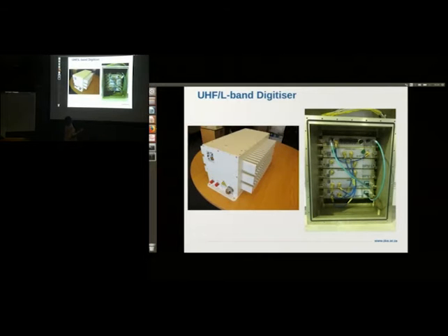Over here is the RFCU, the radio frequency conditioning units. That's the unit that contains the anti-aliasing filters, and these filters are important because MeerKAT makes use of bandpass sampling. So the anti-aliasing filters need to have nice and sharp edges so that no other interference gets sampled down into baseband. So that's the use of the anti-aliasing filters. We've got an RFCU for the H polarization and V polarization.